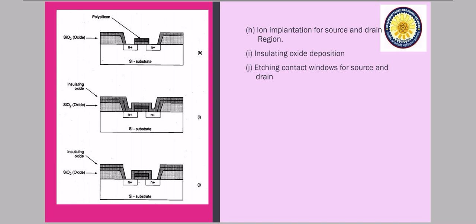Okay, so once the source and drain regions are completed, the entire surface is then covered with an insulating layer of your silicon dioxide.